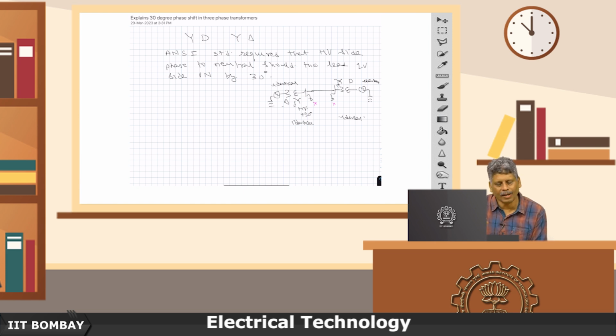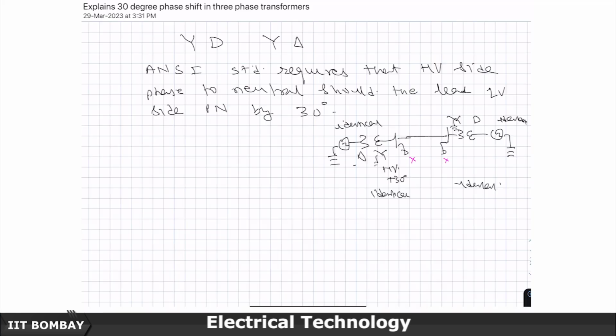Actually in the system there will always be load, but we want to make sure that our connections are such that unnecessary circulating currents are not flowing in the system under light load or no load condition, because everything else will finally only be superimposed on this no load condition to compute the actual currents.